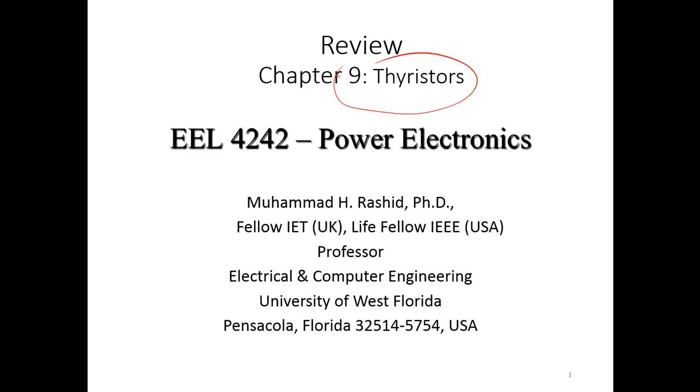The thyristors are basically like a diode, but for a diode, once the voltage is positive, the diode starts to conduct. But for thyristors, even if you apply voltage, the thyristor will conduct only when it's gated. Now that is the oldest device, and that is pretty much matured. And these thyristors are often used for high voltage and high current application.